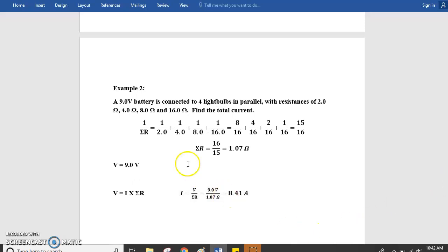Okay, so you're going to be doing a couple of these, 2 in series and 2 that are in parallel. They're not terribly hard. I do recommend trying to work out the fractions on paper, instead of just plugging them into a calculator, just because it's easier that way for me. And don't forget to do that flip at the end, because you need to find the total resistance, not just solve it for the inverse of the total resistance.